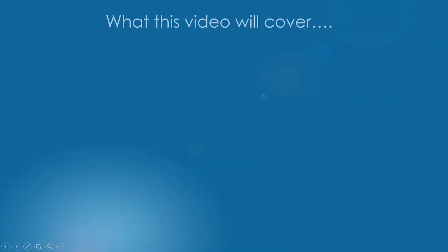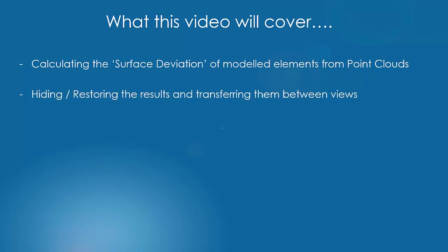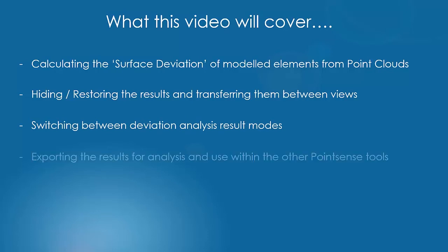In this video we're going to take a look at calculating the surface deviation of modelled elements from point clouds, hiding and restoring results and transferring them between views, switching between deviation analysis result modes, and exporting the results for analysis and use within the other Pointsense tools.